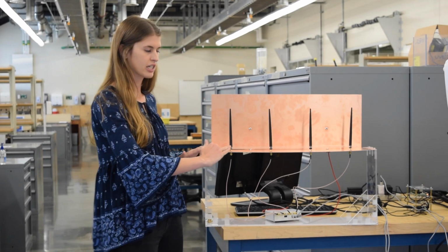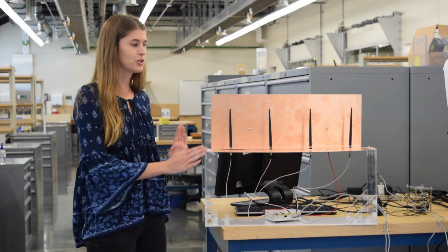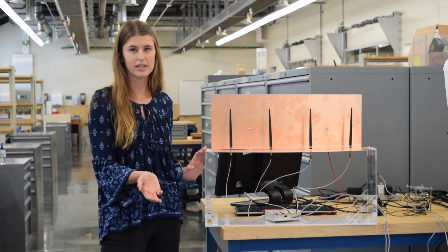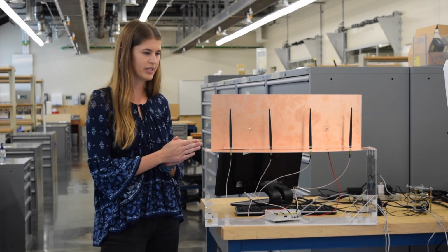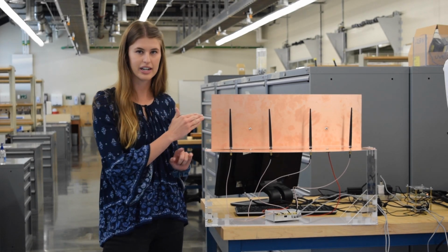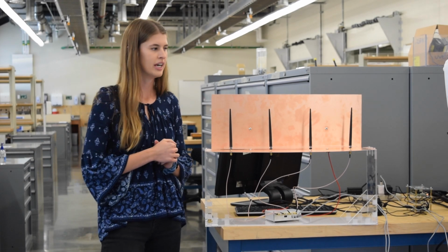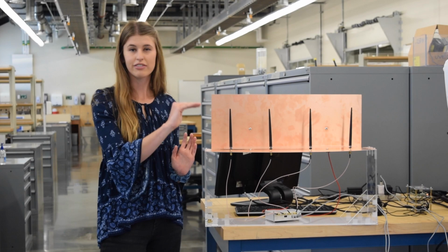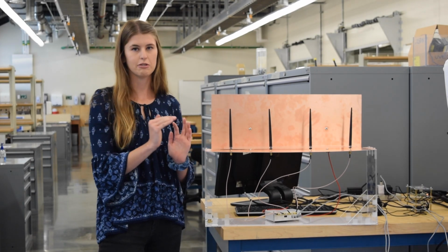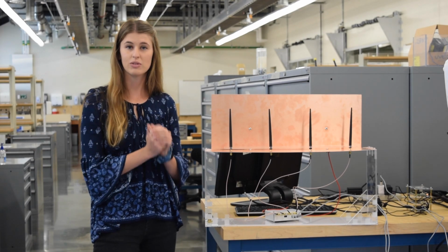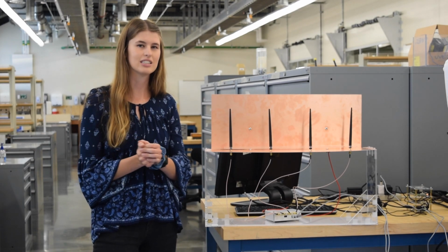So this is a copper ground plane. We chose to use monopole antennas, which need a ground plane. This helps to eliminate multipathing and noise in the signal. The signal doesn't bounce around and hit the antenna multiple times. And we saw that the noise floor without a ground plane was about -5 dB, and with it we can see about -20 dB, -30 dB of the noise floor, which is really good for detecting a nice clean signal.